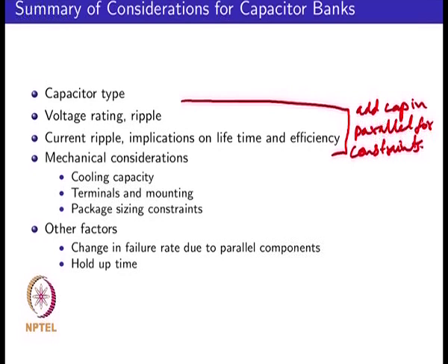So, you effectively help reduce your thermal capacitance as long as you keep your packaging space between capacitors constant, but you also have mechanical constraints of volume and size, which means that you cannot go on increasing the number of devices that you could add in parallel. You end up taking a lot of space. So, from your packaging constraint, you might have sizing requirements which might prevent you from adding more capacitors.